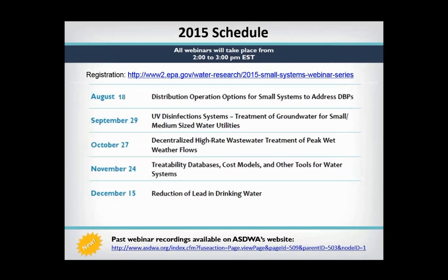Okay, here's a second question for you. Aeration can be effective for some water quality conditions. I'm curious why aeration has not been addressed as a treatment method. I think the expectation was that it's encompassed under pH and alkalinity adjustment, because aeration really is basically both. I think it wasn't called out as a specific technology because it's got limited applicability. Certain water qualities it will work well, other water qualities it won't. But it's certainly intended to be an effective measure, and we know it can be a very effective treatment.